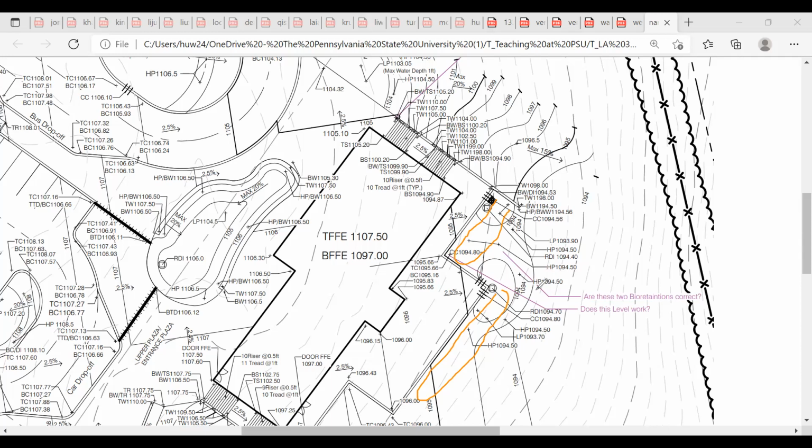Also, in reality, most of the design would opt for just sheet flowing to the vegetated area. Yes, there could be some salts during the winter, but the pollutant profile is pretty limited. So most of the developers or designers will be okay and say, let's just drain it to the side.